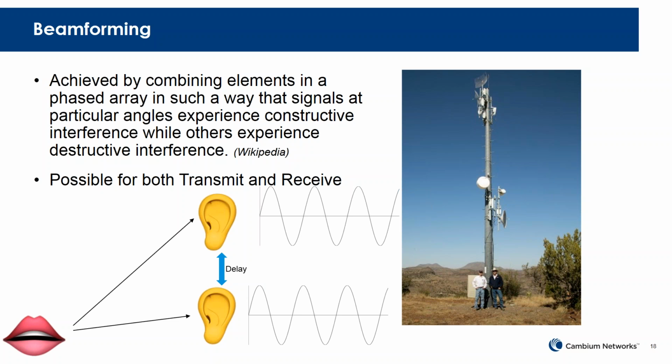And in wireless, we call that offset a phase shift. And what our brain does is it takes that delay and offsets for it, it compensates for it. If there's someone to our left, you don't hear an echo, because you heard two individual signals. Your brain actually takes those two signals, compensates for them, and then combines them together. And the same can be true with wireless with beamforming, where you have two individual receivers. They're spaced apart, similar to ears, and it's a set amount of spacing. They're very precisely spaced. And as we receive, we can take those two and we can compensate.